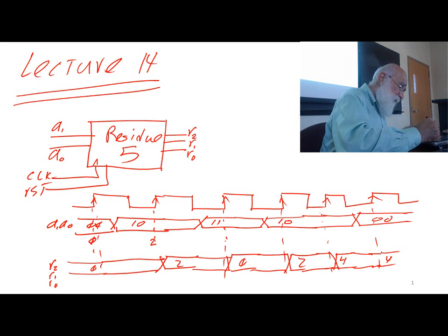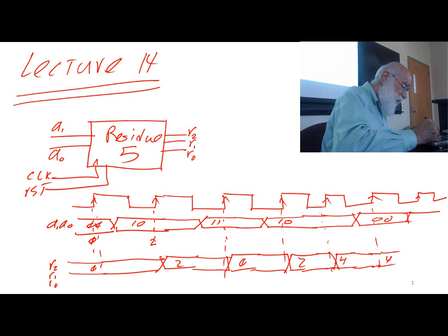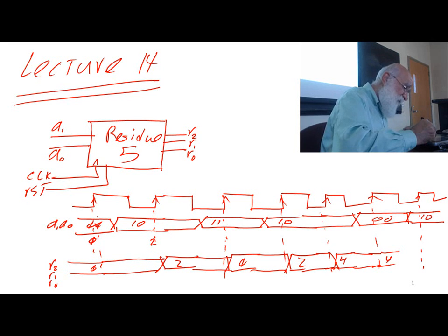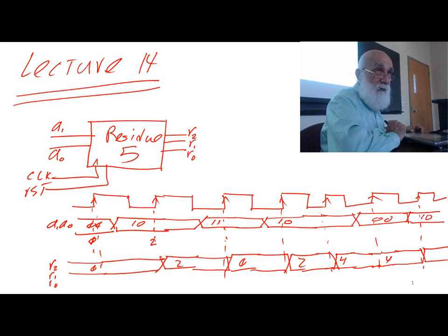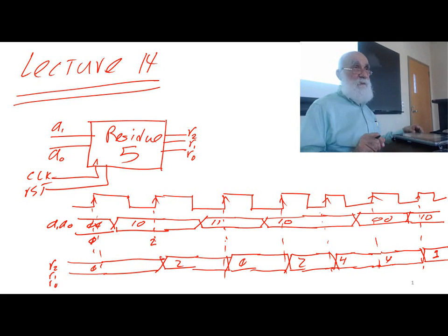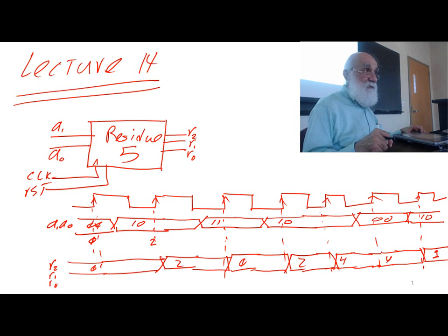All right, so let's do one more pulse here, and let's say at this point my input has changed to 1 0, and then I have 4 plus 2 added, and therefore what does my residue become? 1. See, 4 plus 2 divided by 5, the remainder is 1. So this should be pretty much a good representation, or a good example, for the behavior of this circuit.